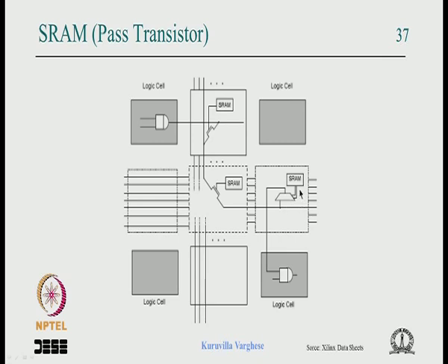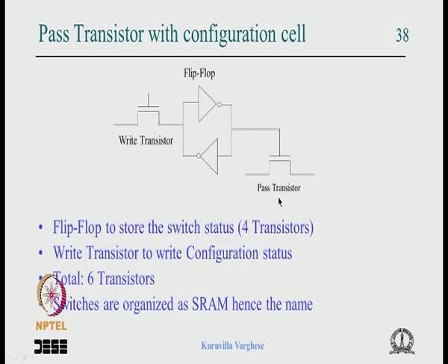So you can imagine wherever there is a switch there is a flip flop. Now you cannot program these flip flops individually, so what is done is that these flip flops are collected together as a static RAM or a memory which is 8-bit or 16-bit wide. In the previous generation it was 8-bit wide memory, in the current generation it is 16-bit wide. So to program means you write to this configuration memory which is SRAM, but the real interconnection technology is a pass transistor in an SRAM type of device.